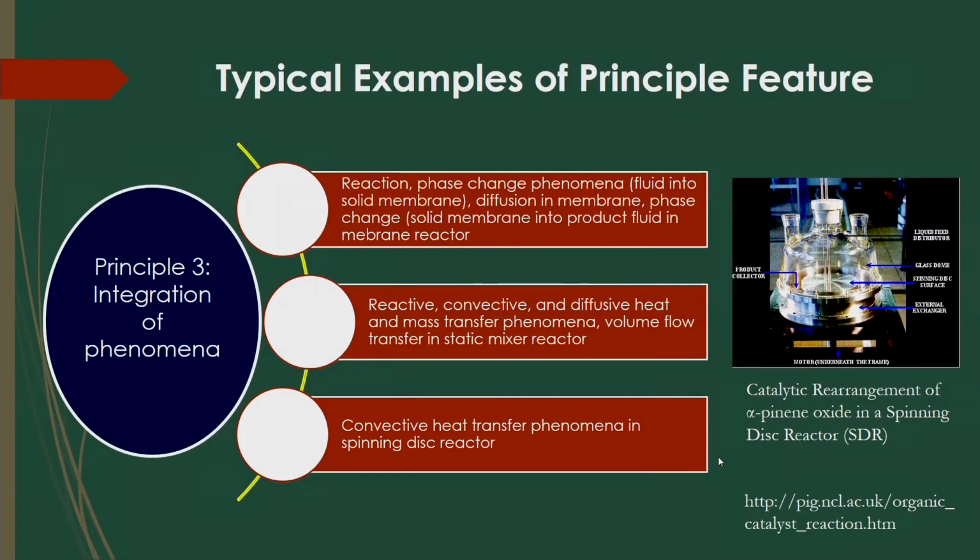And also in a static mixer, the reaction phenomena, convective and diffusive heat and mass transfer phenomena will happen there in an intensified mixing way. And sometimes in a membrane reactor or some porous reactor, there will be a phase change of the fluid in the reactor, and you can also intensify the diffusion of the molecules in the membrane reactor. And through the porous material you can enhance the diffusion of the process. So, that is why these phenomena have to be considered in an integrated way to get the process intensification.